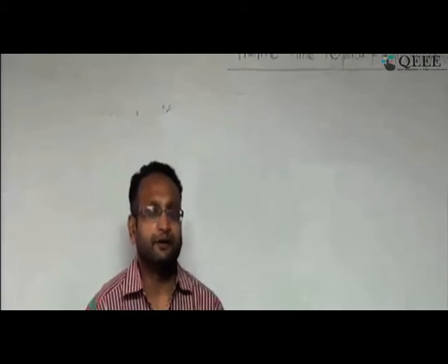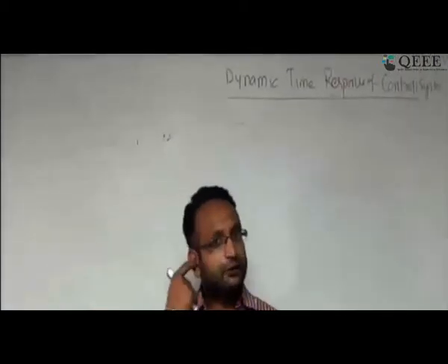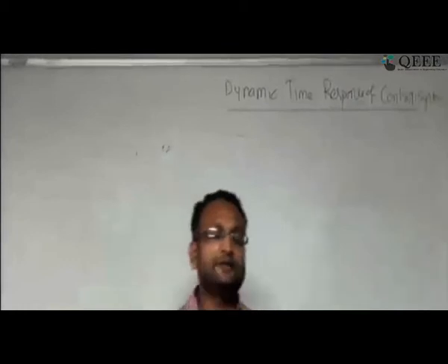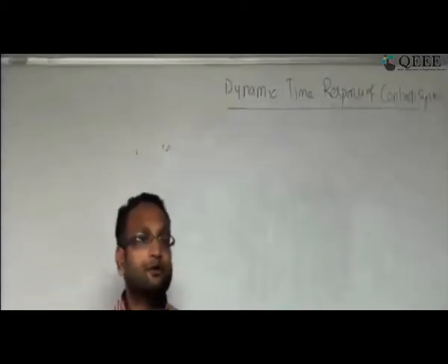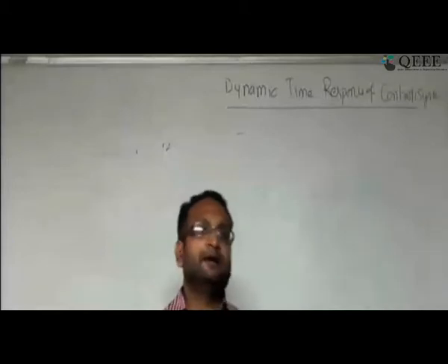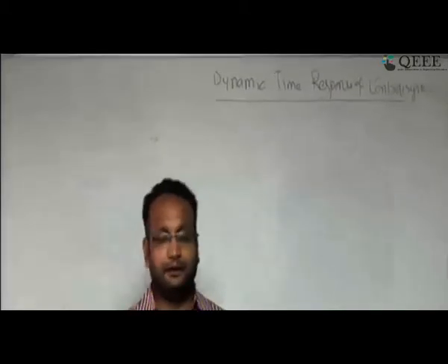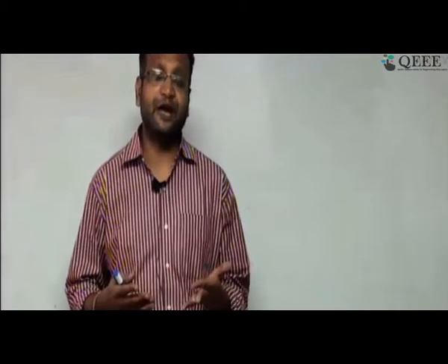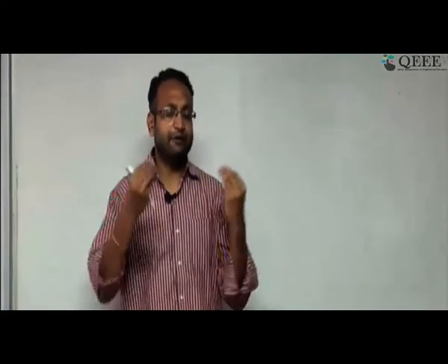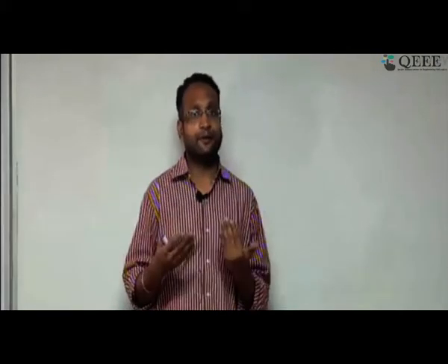Okay. Fine. So what I have explained is the effect of different controllers, the two types of controller. One is a proportional controller, the other an integral controller, and how they are affecting your time response. And there are pros and cons in the proportional controller. Yes, the system becomes faster, but here you may not get a steady state value of one. You have to use a very high gain. But in practice, that is not going to be a feasible solution, because in practice the systems are typically very high order. If you increase the k, the poles of the system might go to the right half plane, and your system becomes unstable.